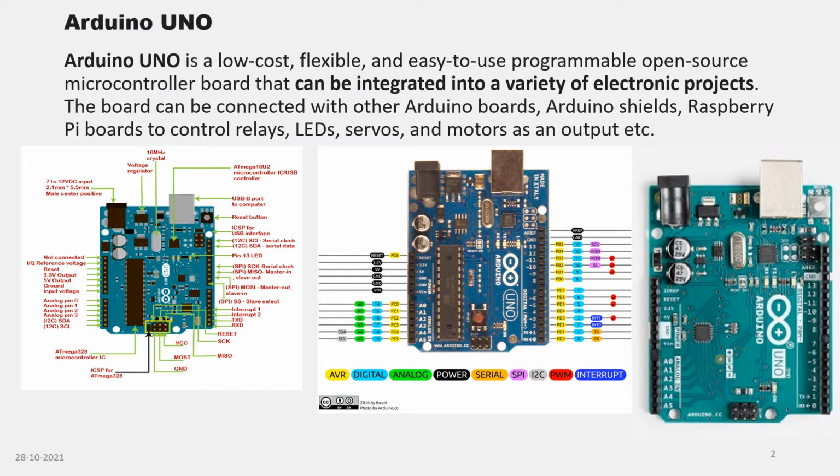About 6 pins are labeled PWM, that is pulse width modulation. They are digital pins too, but they are used in getting analog results through digital means. If you want to get analog results through the digital pins, you make use of pins 3, 5, 6, 9, 10, and 11.